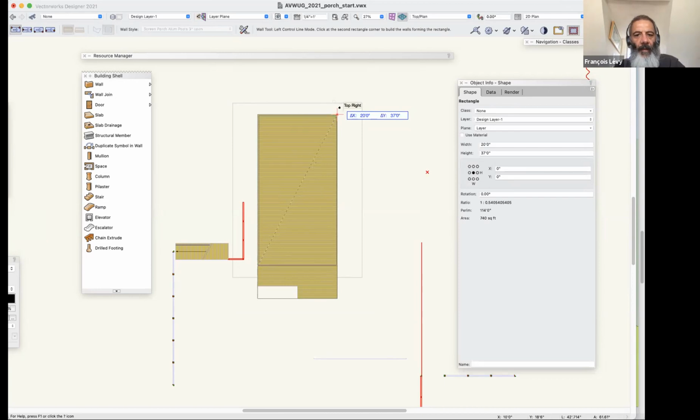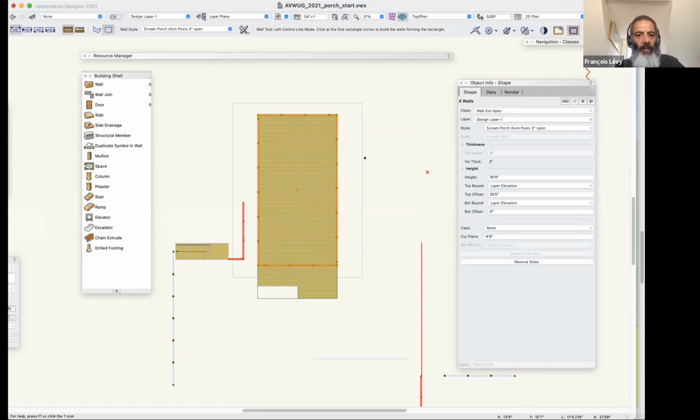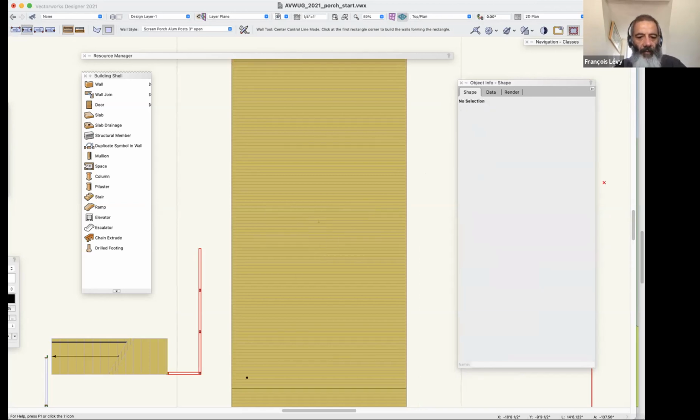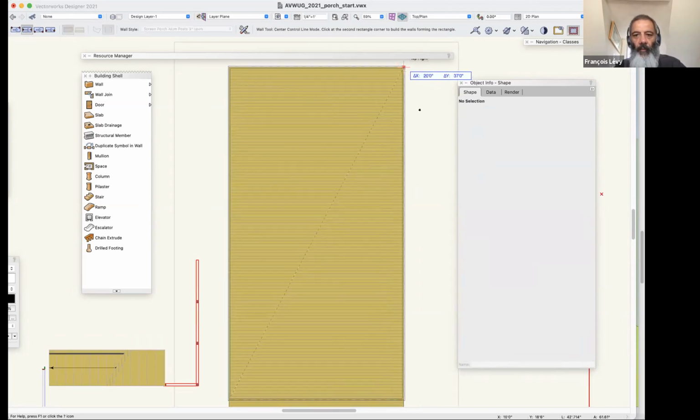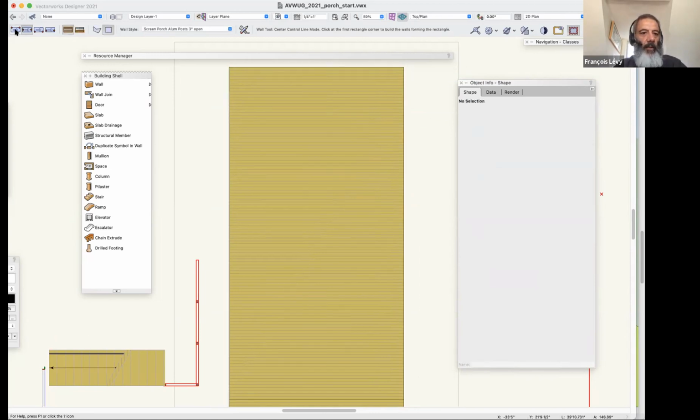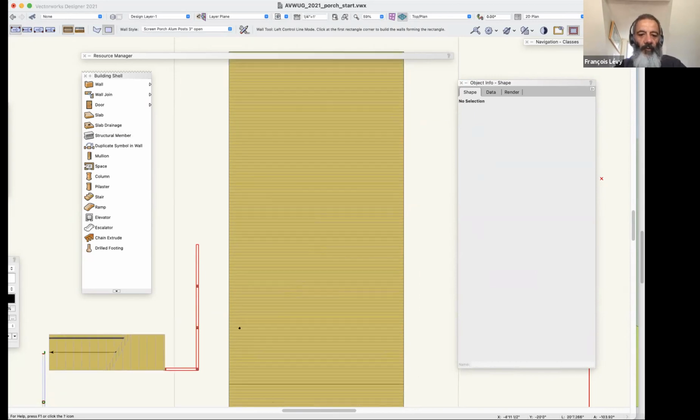So if I snap this way here and draw it as a rectangle, it'll take a minute for that to do its thing. I'm drawing it from the left side, which by convention is the outside of the wall. And so then those four walls are within the boundary of that rectangle. If I just delete that, and say draw it from the center line, then obviously they're going to be centered on that guiding rectangle. Generally speaking, you're going to want to draw walls from the left side.